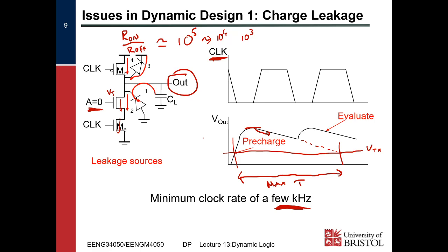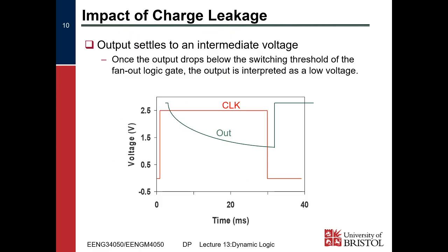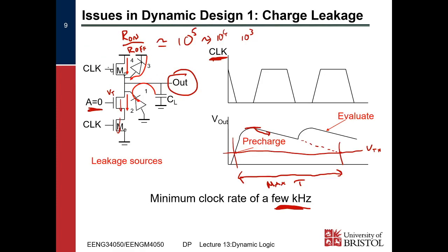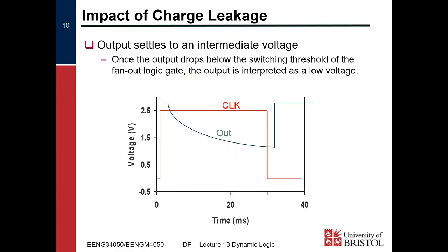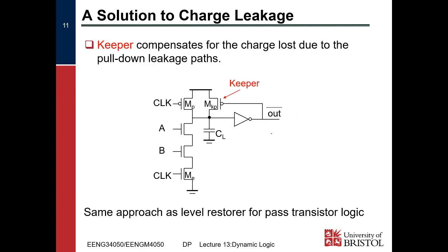Obviously, we can just turn the entire circuit off and say we don't care what our output signal is. But if we want to maintain our output signal, we must, at the very least, maintain this minimum pre-charge frequency and this minimum clock frequency. So we see, yes, our clock goes high and then low. While our clock is high, our pre-charge transistor is off. Our output decays exponentially until our clock goes low again and our pre-charge transistor turns on.